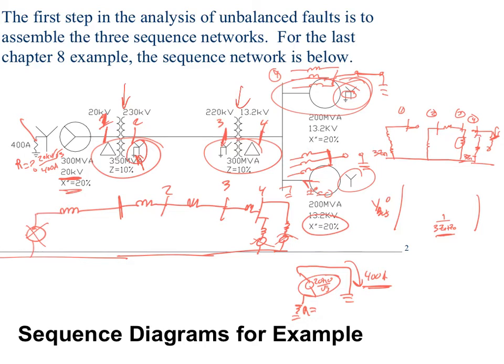The problem is if you have a ground fault over here and the utility has set their system with 67N elements, then this one right here, which is what the owner of the GSU has to set, they have to coordinate. So that's one of the hiccups in getting all this stuff coordinated, because the generator owners own the generator step-up transformers.